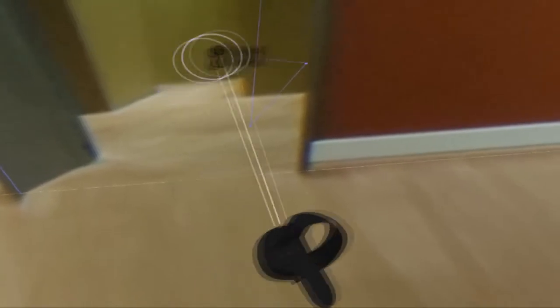Bear in mind that when contouring, you can add anchor points to other lines for easy alignment, but you cannot let your lines intersect and cross. When they do, they will glow red, giving you an error message. Think of it like Ghostbusters. Never cross the streams. Like before, just close the loop, and there it is.